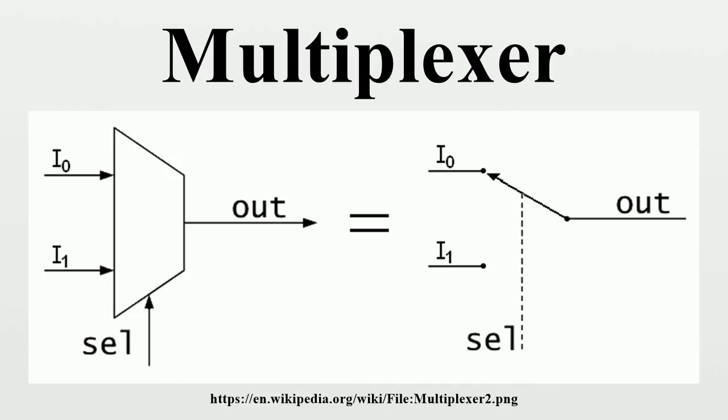An electronic multiplexer makes it possible for several signals to share one device or resource, for example, one A/D converter or one communication line, instead of having one device per input signal. Conversely, a demultiplexer is a device taking a single input signal and selecting one of many data output lines, which is connected to the single input. A multiplexer is often used with a complementary demultiplexer on the receiving end.